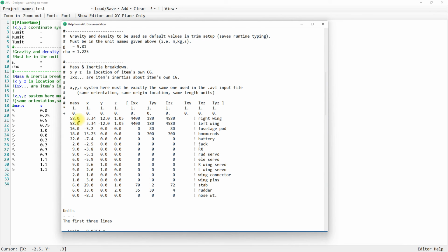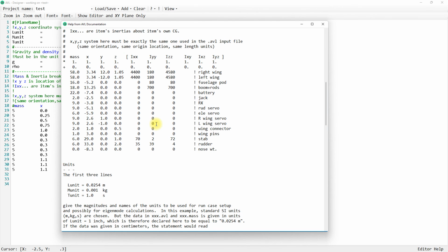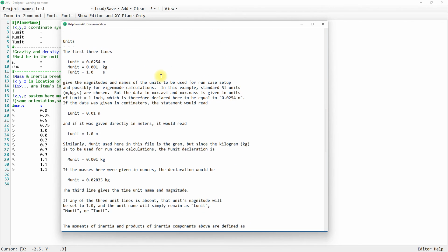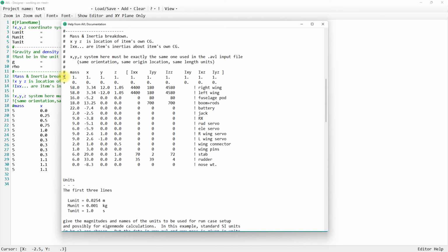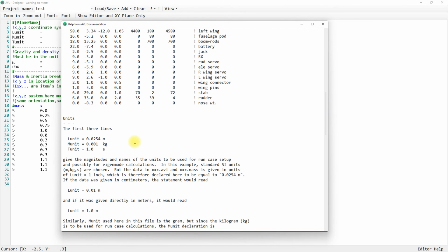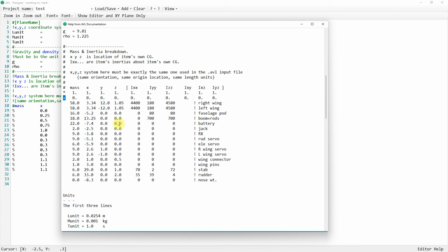Something else that we did not include in this is you can also add information on scaling or shifting the points. For example, in this sample that is provided in the help file for AVL, you can see that if a line starts with a star or asterisk for multiplication and the plus sign for addition or offsetting the points, you can add the following points with those operations to scale and offset the values that you have.